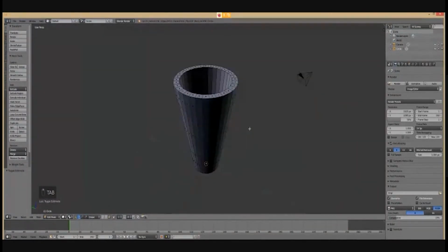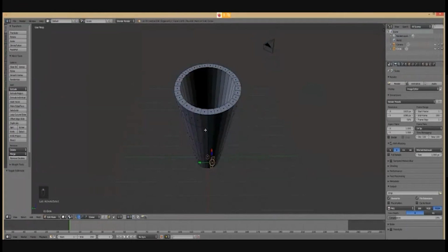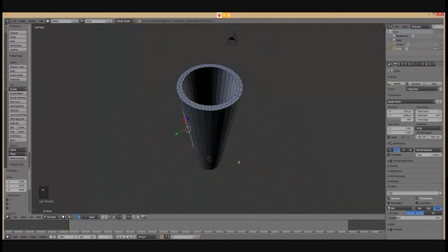I'll explain it to you by taking another handle over here. Okay, so I'm in edit mode right now. I basically made a single face into three parts. That part you understood, right? I used a loop cut. I got these two lines. Then what I did is that I chose two faces such that they are parallel to this axis, or I could have chosen even, for example, these two faces, as long as they are parallel to an axis.